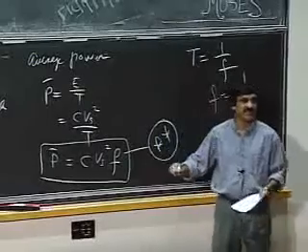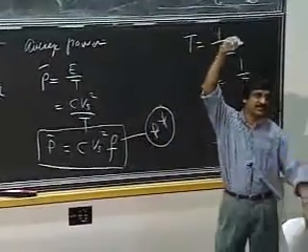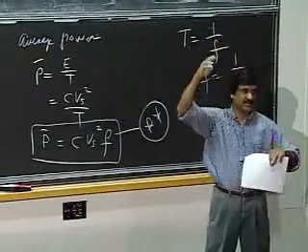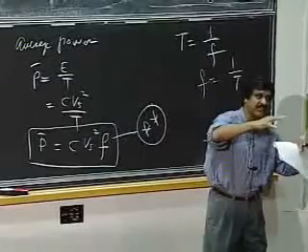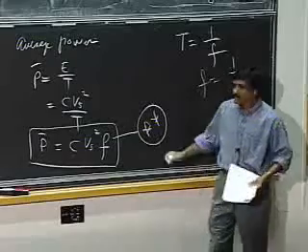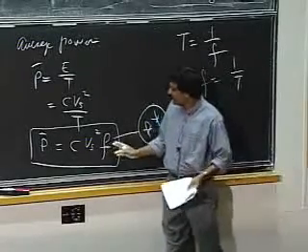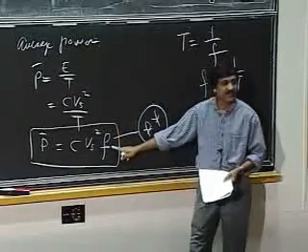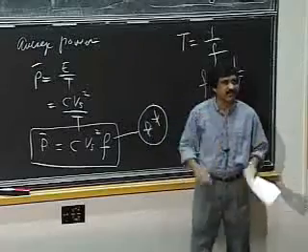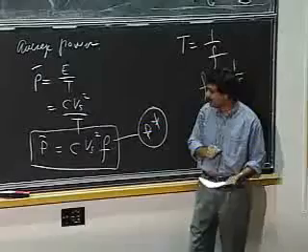Notice that at any given time, there is no direct connection between the power supply and the ground. What I'm doing is my capacitor is an intermediary. I'm dumping some charge in the capacitor, and the capacitor is dumping the charge into ground. It behaves like a switched capacitor. And it's being charged and discharged at frequency F. So it makes sense that the average current I'm pumping through relates to the frequency at which I'm charging and discharging the capacitor.